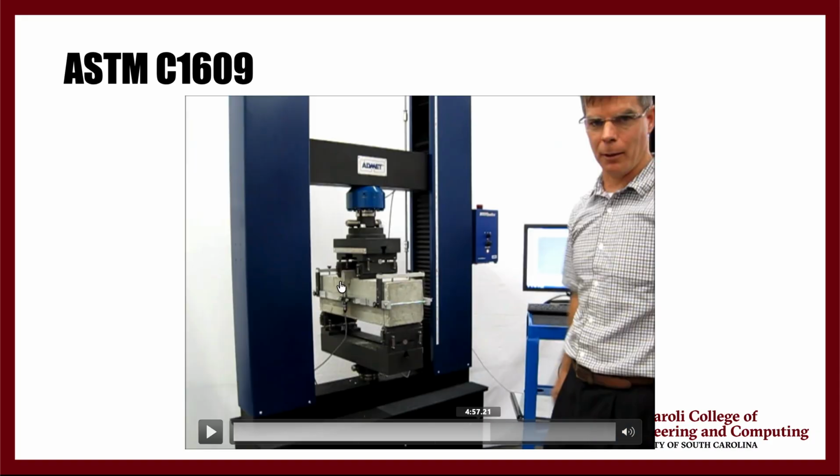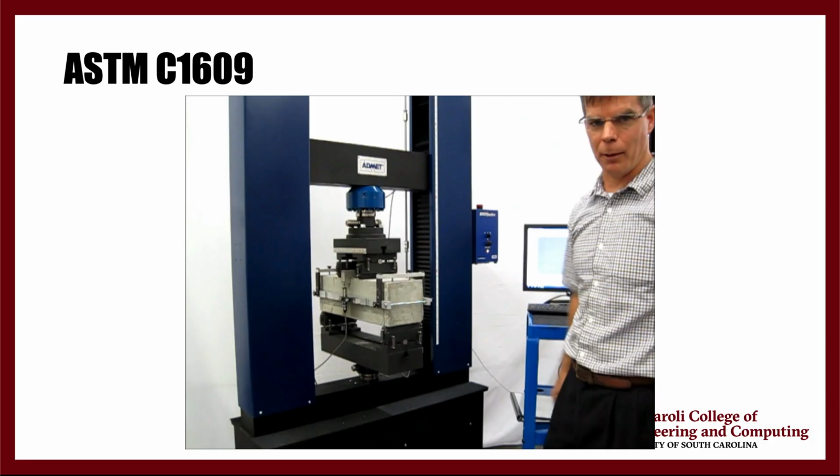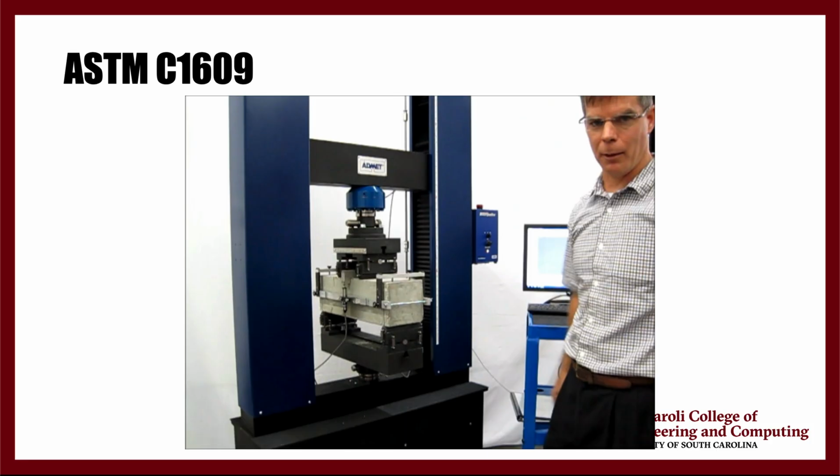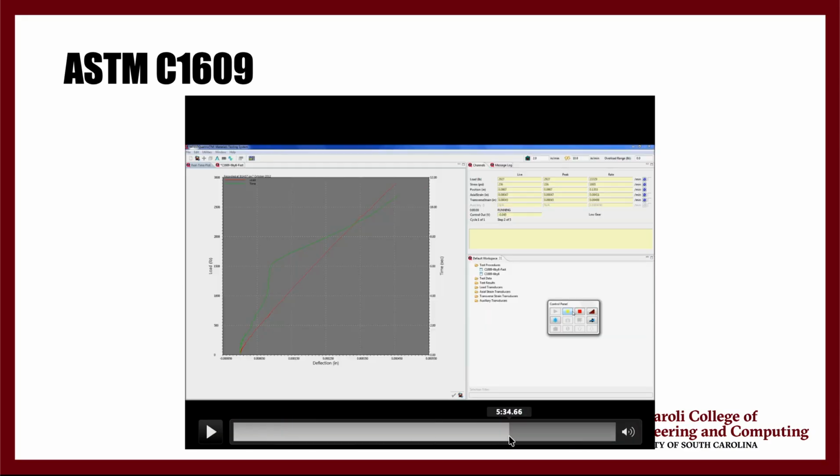This is where the forces are being applied, and these are the 2 supports. This type of bending scenario is called 4-point bending. Pretty simple. We have 2 supports, 2 points at which we are exerting the force. This 4-point bending can help us understand the strength of concrete in this specific example.